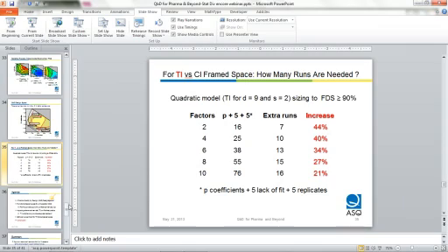It's becoming more and more commonplace to use such things as finite element analysis on the design of turbine engines and so forth, and then applying against the simulation an experiment such as a response surface method, perhaps an optimal design. Typically, you end up over-specifying the model points so that you get a better coverage of the space, or you use such things as Latin hypercube designs. And then you pull out what's called a transfer function from that, which simplifies things quite a bit. And then from that, you develop a sweet spot.